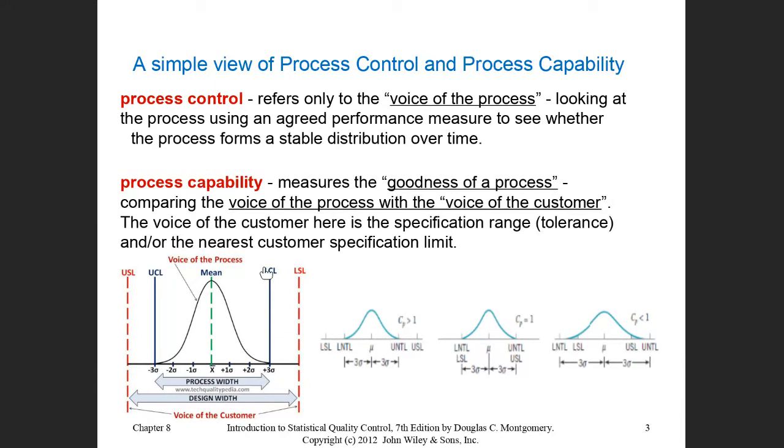This chart shows the relation between the control limits, which we used in the control chart in blue here, and the red dash is the specification that is set by the customer. Usually, to have acceptable production or service, your specification has to be wider than the control limits.